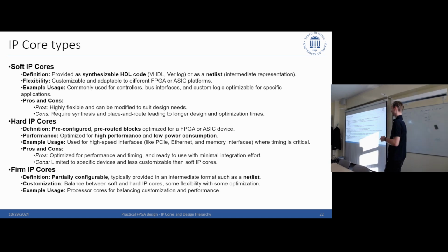The soft IP core is, of course, wonderfully flexible. You can customize it, you can change it, you can adapt it, especially if it's written in HDL code, where you can just go in and change things. However, consider that it's a verified core in many cases. You do not want to change too much, otherwise you have to test everything again.